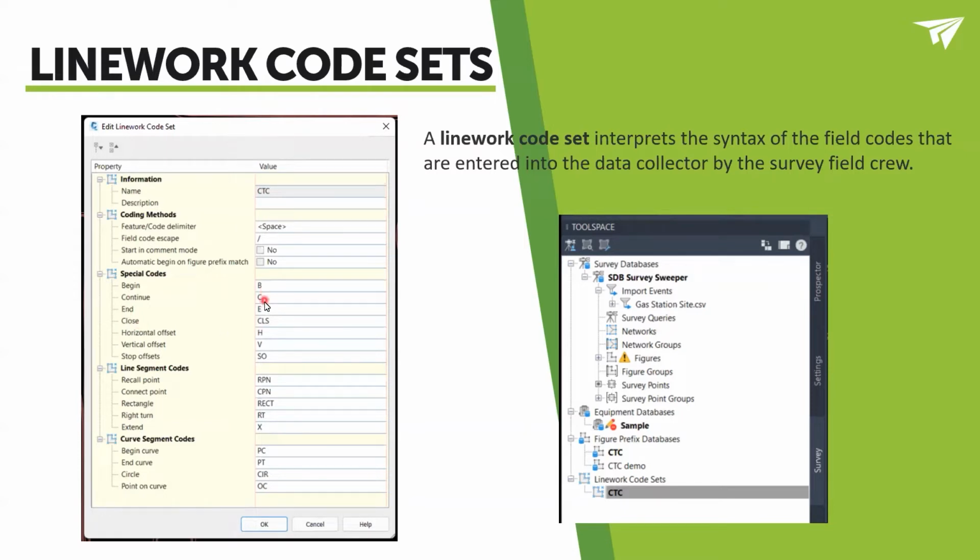They have a few here that we're going to use today and showcase, specifically begin, end, and close. These specific letters are going to be added to the end of our codes when we get them in from the field. This is going to indicate that yes, we have a code set, but also where our line starts, where our line ends, etc. You see that we have quite a bit of options here to choose from. We can update these as we want to, as well as add any additional codes.